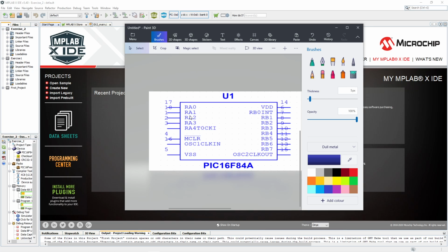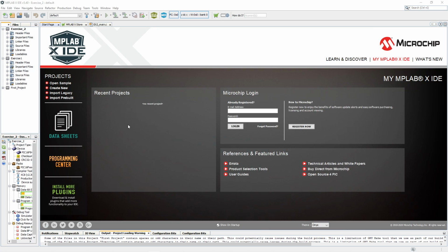Now, this is very important when you work with MPLAB, because MPLAB does not give you diagrams and does not explain to you how many ports are in there. So when working with MPLAB, you need to have a second diagram, or the original diagram of the microcontroller. Look through it carefully, because as you'll see soon, you need to know the number of ports to do a proper input, output, and so on. Now that we've seen the diagram, and I'll pop it up when we need it, for now I'll just put it down here. Let's create our own project now.